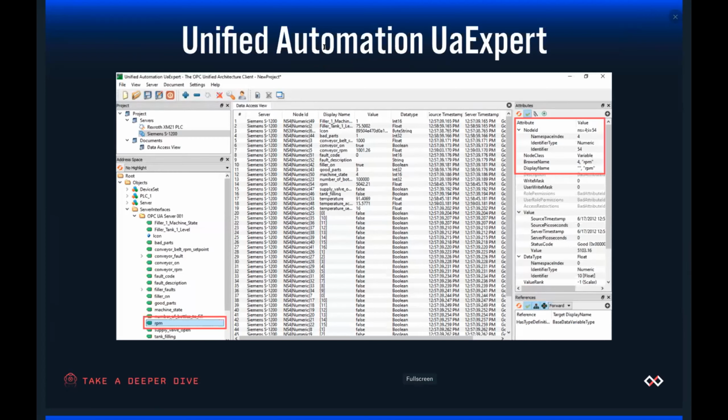So a really quick pro tip to get that information, that namespace and identifier type, really quickly, if you don't already have it on hand, is this Unified Automation UaExpert tool, which you can download online and you can connect to your IP. And then you can see here, I have highlighted already RPM, which is one of the tags that we're interested in. And then over on the right, all that information that I need, that namespace, the index, the identifier, that's all right here. I don't have to look very hard. It is present and I can take that information and run with it.